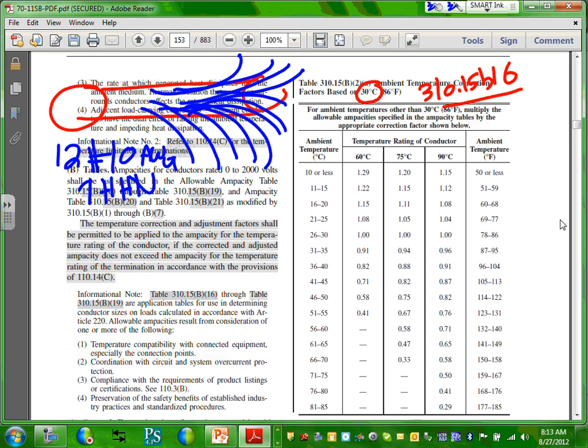Okay, so here's what you're going to do. We're going to take number 12. Since it's THHN, you're going to go to the 90-degree column. With me? How much current can THHN number 12 carry? I can tell you 30 amps. Why did we go to the 90-degree column? Because we're derating. Cool? Everybody can give me a thumbs up, Chad? We know why we get that.